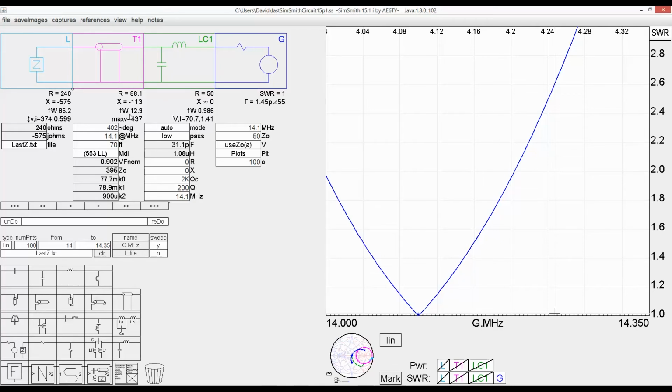But then look, we're losing almost 13 watts in the transmission line, and then 86.2 watts are making it to the antenna. I remember when I first started playing with this it was a bit of an eye-opener, because I had always thought that ladder line, especially ladder line, would have virtually no loss at high SWR. And it's way better than coax, that's for sure, but it is a finite amount.